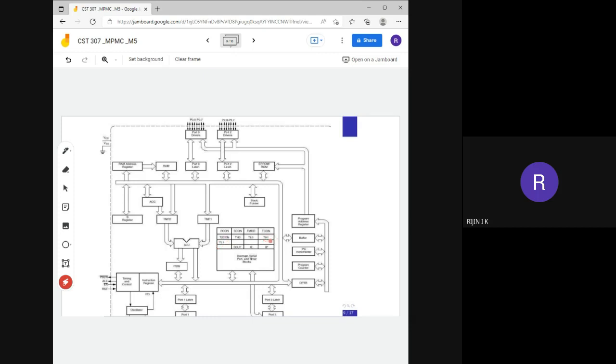That means it is a 16-bit register. Lower order 8 bits are TL1 and higher order 8 bits are TH1. Then here you can see a register that is SBUF. This SBUF is used to hold the data while transferring in serial communication.